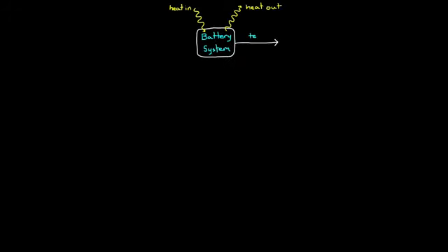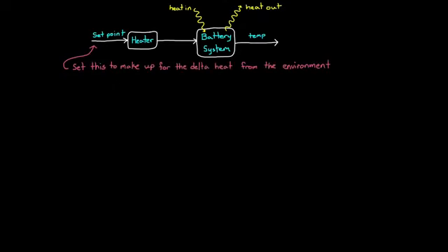So where should we go from here? Well, if we knew the battery system perfectly, that is, how much heat enters and leaves the system while on orbit, and we knew how the delta heat changed the temperature of the battery system, then we could just set the heater to the proper supply value to make up the difference and be done. This is an open loop control design because the heater set point doesn't rely on feeding back the battery temperature.